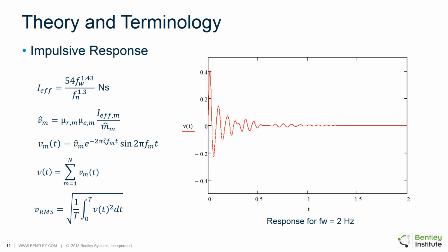And then we can use that walking frequency in the next equation to calculate a modal velocity for each mode. And we can do that by using the mode shapes for unity normalized mode shapes. And we can apply an excitation location and calculate the response at any location we like. And for that, we can calculate a velocity for each mode.